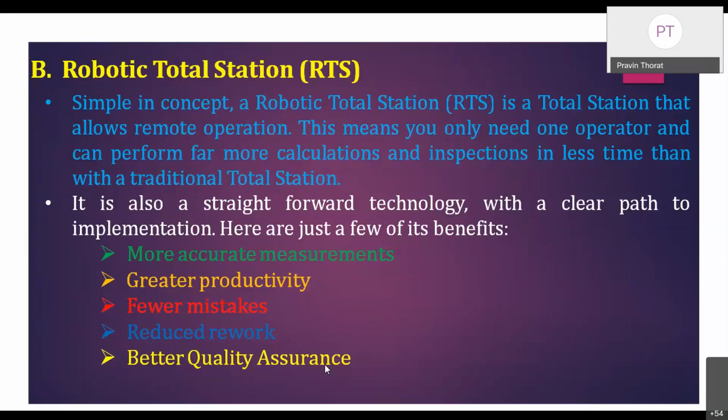This eliminates the need for an assistant staff member, as the operator holds the reflector and controls the total station from the observed points. The remote positioning unit, which is attached to a prism pole, has a built-in telemetry link for communication with the total station. Even a prism is not needed near the total station. The total station automatically moves and locates the target.